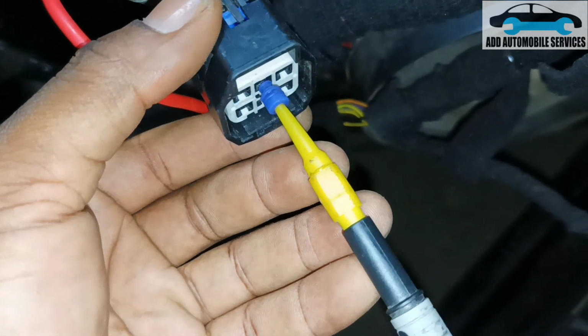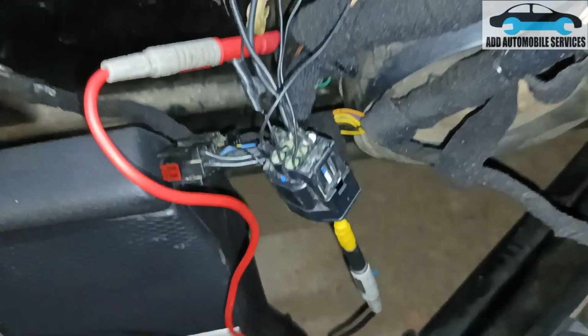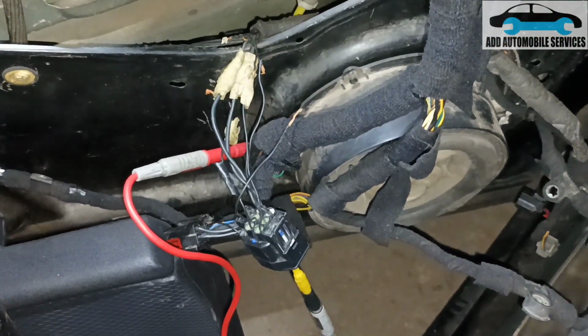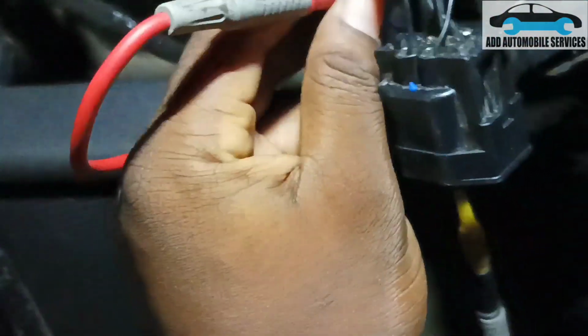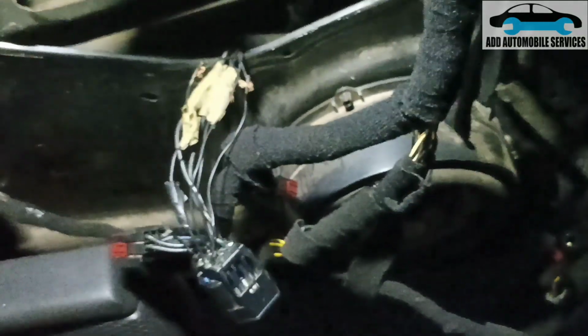So now it's left with 5 and 6. So I'll do 5 and 6. Then all the pins will be right. Then I'll plug everything back and test it. So now I'm done with all the pins, and pin 5 and pin 9 are still beeping. So what I'll do next is plug the socket and plug the control in it and test everything. Then I'll call it a fix.